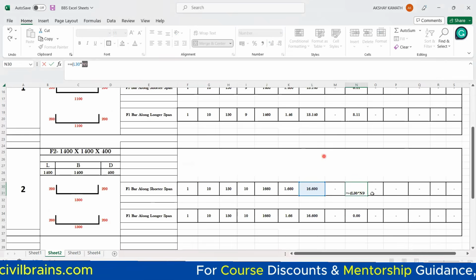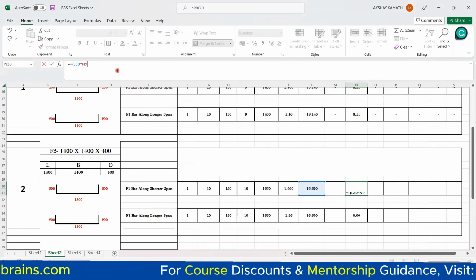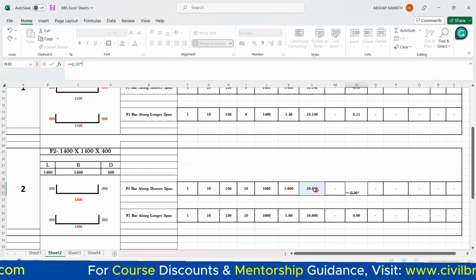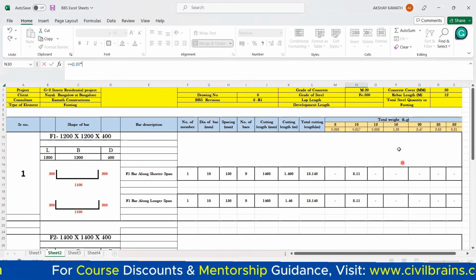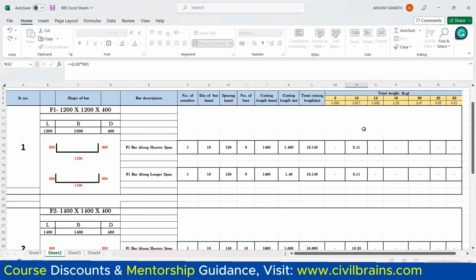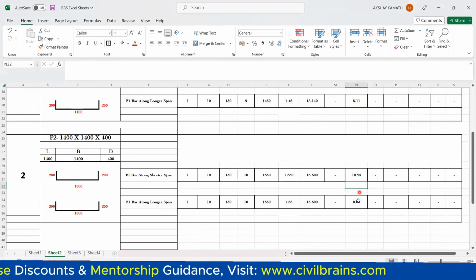Wait, come here. Okay. Multiply this by L30 is this one. That is total cutting length. We'll multiply the total cutting length with the unit weight of a 10 diameter bar and hit the enter button. Finish. You got 10.25 kg.